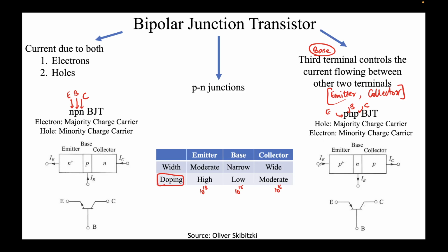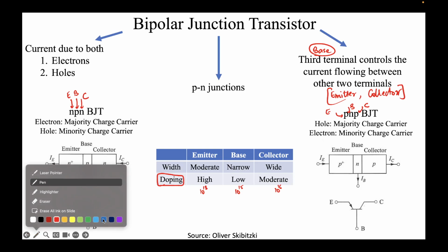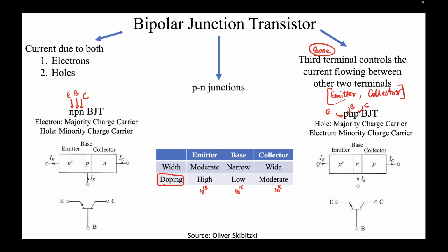What we typically do is connect, I had not drawn this because I did not want to introduce the biasing as of now, but since the doubt has arisen, we connect something like this, forward bias. P is connected to the positive terminal, so the current will flow in this direction. Forget about the collector for now, focus only on the emitter base junction. Current will flow in this direction, and this is how we denote a PNP.